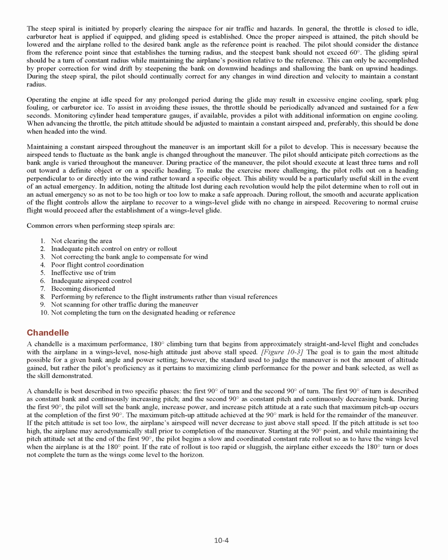When advancing the throttle, the pitch attitude should be adjusted to maintain a constant airspeed and, preferably, this should be done when headed into the wind. Maintaining a constant airspeed throughout the maneuver is an important skill for a pilot to develop. This is necessary because the airspeed tends to fluctuate as the bank angle is changed throughout the maneuver. The pilot should anticipate pitch corrections as the bank angle is varied throughout the maneuver.